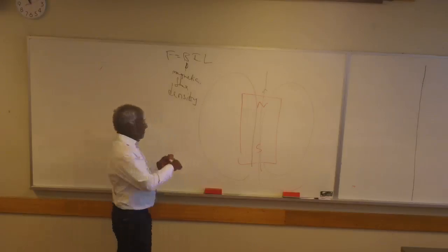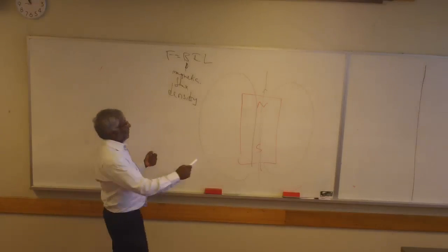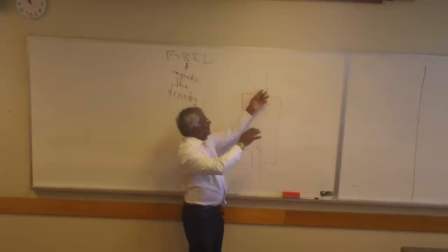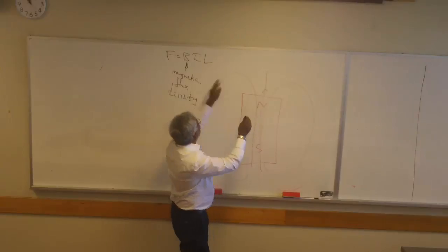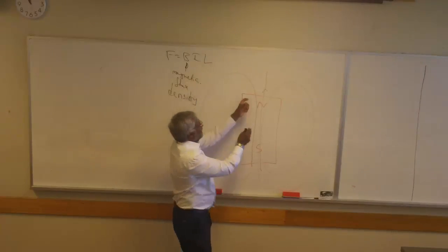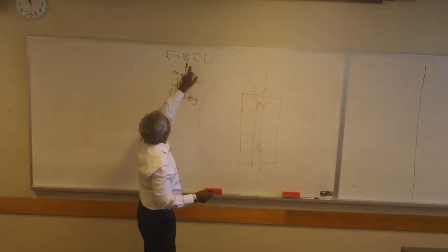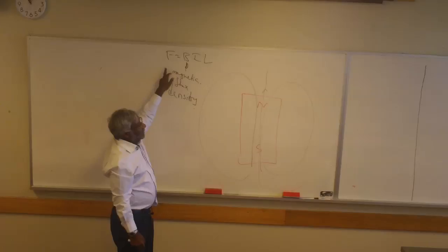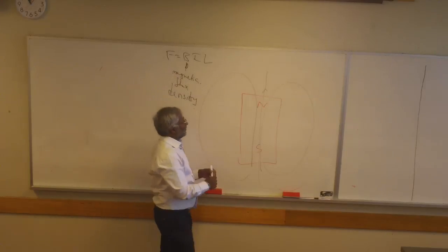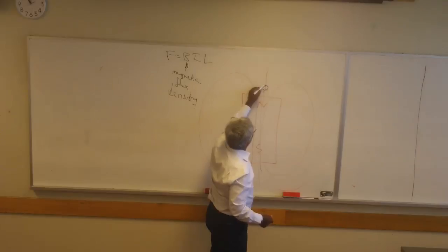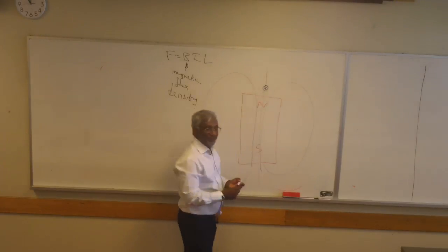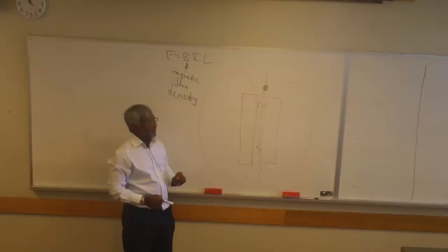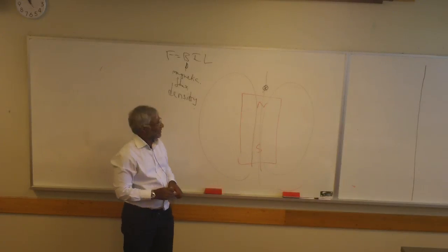So, we're putting numbers in now. If I wanted to measure the flux density here, I would just take a wire of an appropriate length. If it was a small magnet, I'll use a smaller piece of wire, and put 1 amp through it and measure the force. Hopefully you've done a bit of physics and you know that if you had a current here, say going into the board, so you had a conductor with a current going into the board at this point, there will be a force on it. In what direction would that force be?